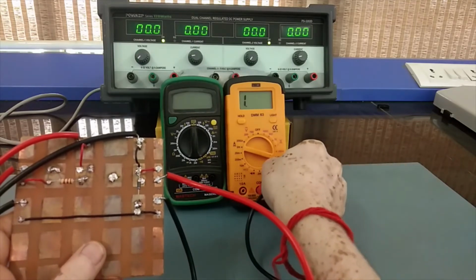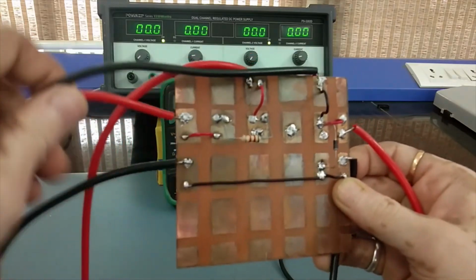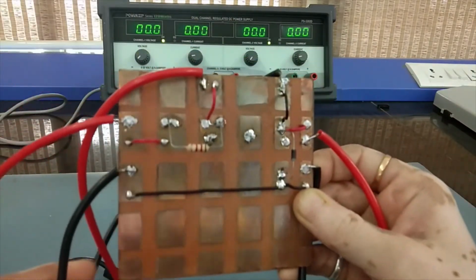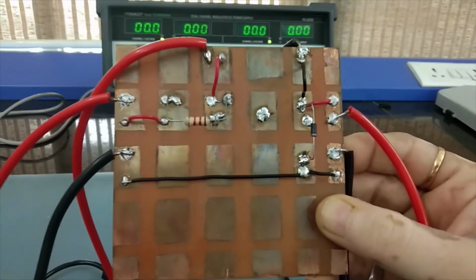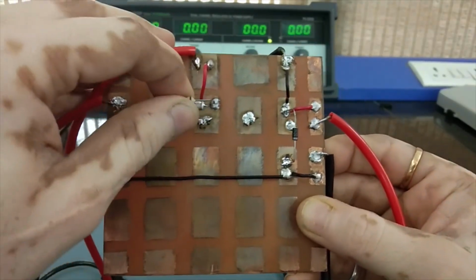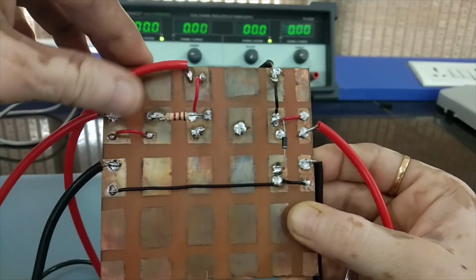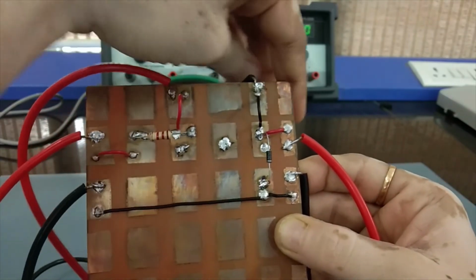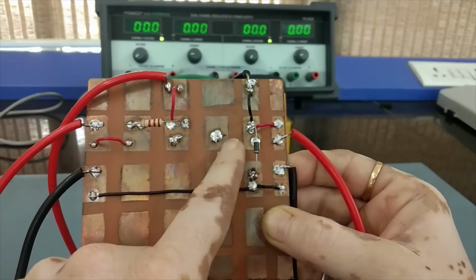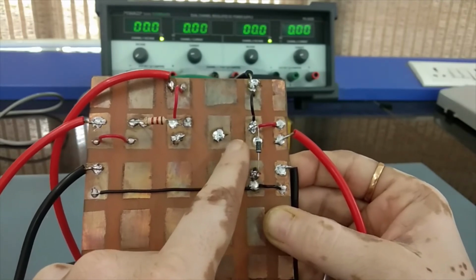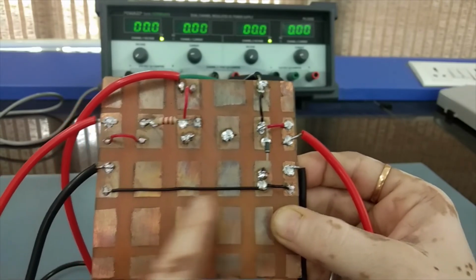Alright, now we will build the circuit. We have already told you about the circuit. So we have already built it. There is nothing very serious in this. Resistance is there. One side of the resistance is connected to the power supply. Other side of the resistance is connected to the positive of the ammeter. From the negative terminal of the ammeter, we are feeding the diode, anode in this case, and if it is in reverse bias, we will be feeding the cathode of the diode. And then cathode of the diode in this case is connected to the common ground.